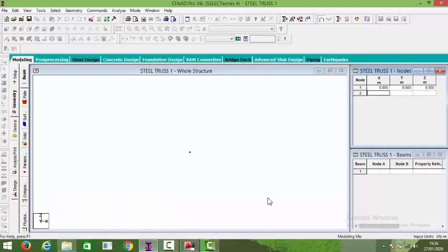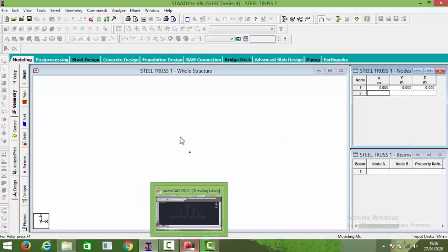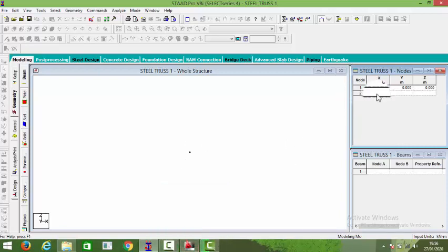This is your X, so you are moving X 1.5. You are neither moving up nor moving in. So our X here is 1.5. We specified at the outset that our entry will be in meters and kilonewton, remember? Use tab to go forward. They are all zeros.